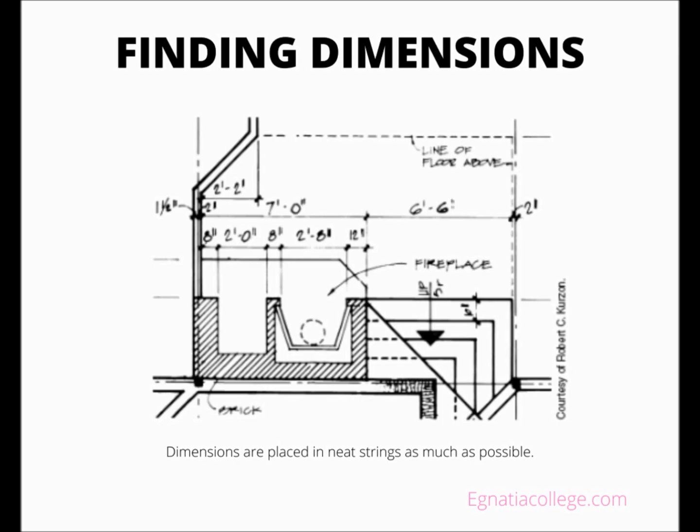As each wall is laid out, the plates are cut to length, and the positions of all openings and intersecting walls are marked. The wall frame is usually assembled flat on the deck. Its position is marked on the deck with a chalk line, then the assembly is tipped up and slid into place. Commercial buildings may require a thicker wall, where the electrical service panel is flush mounted, and the panel box is deeper than the standard 3.5 inch wall. Many times, this thicker wall requirement is not shown on the floor plan or drawing details.